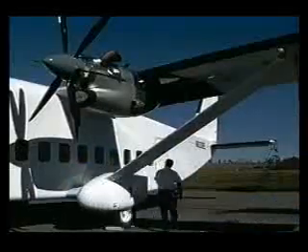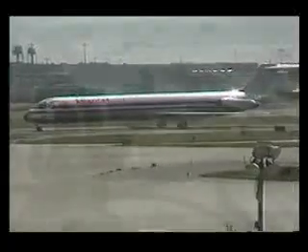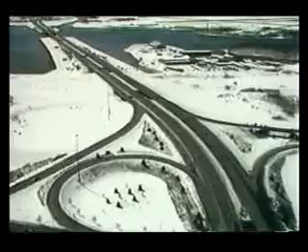But be careful when selecting this baseline aircraft. For example, let's say you have 10 -7 aircraft in your fleet, with the oldest being 12 years old and the others between 8 and 10 years old. If you pick the older aircraft based solely on age instead of operating history, you may find little corrosion. That 12-year-old aircraft may have been recently purchased from an airline which flew only from Albuquerque to Phoenix, while the others may have spent their entire operating life in the Aleutians.